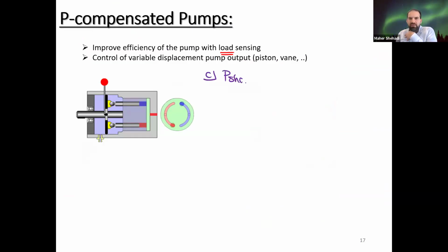So P shaft, it's T in inch pound times N in RPM over 63,025, and that's equal to 25.2. It has to be in horsepower to have the units.